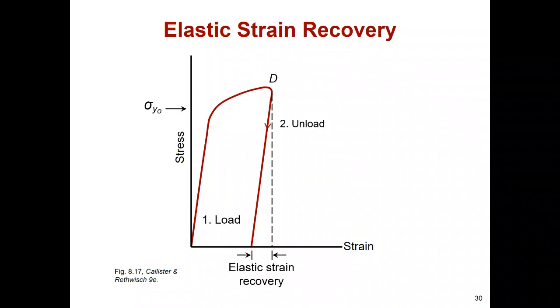These slopes are the same as when we applied the forces in the loading. So we say that this is elastic recovery. After that, we apply forces again. They go to some yield strength, but this strength value is increased compared to the first loading cycle.